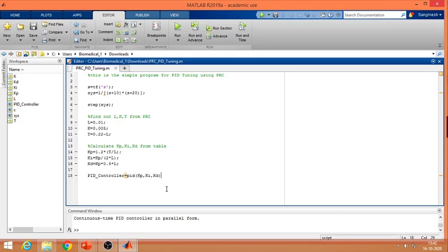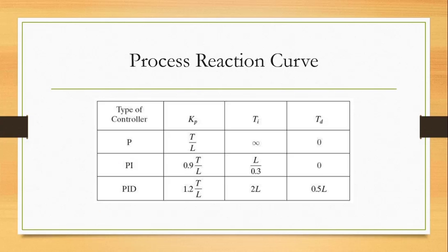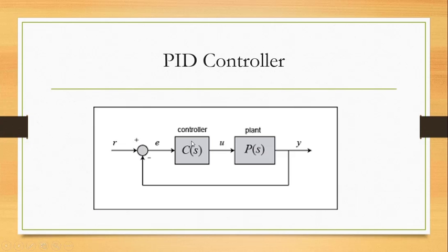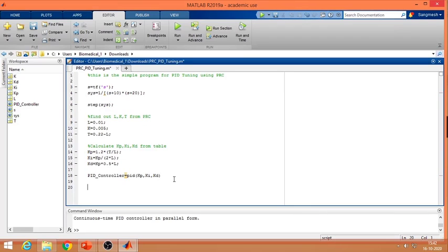Now let's come back to this PPT and let's see here. We get this point now, the controller design is done. Now plant and controller. Let's take one complete open loop transfer function of these two. That can be easily obtained: open sys is equal to series of PID controller and our system. So this gives me the complete open loop transfer function. It is a multiplication of PID and our system.